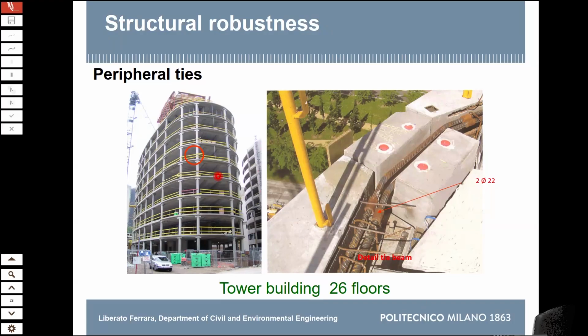The panels, in case, because you rely upon the continuous support. But if one fails, what happens? You must have some hanging reinforcement. And this hanging reinforcement can also be a loose one, which is mechanically anchored. You do not rely upon bond, because in that case it does not work until that moment, and it is immediately activated when the movement due to the loss of support is activated.